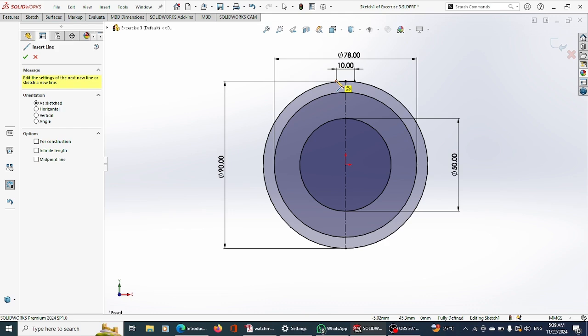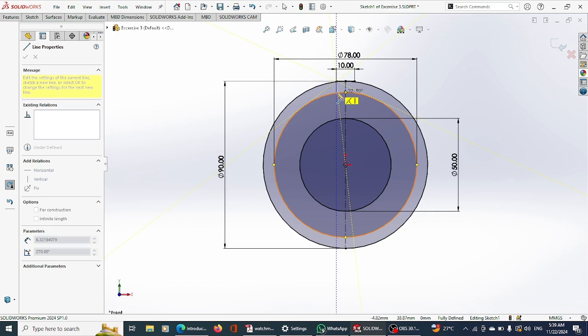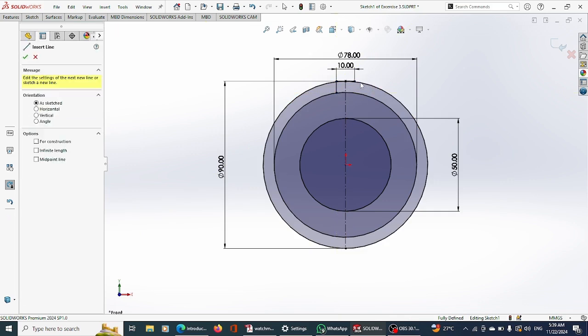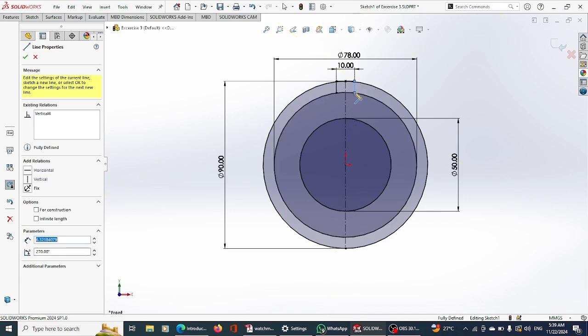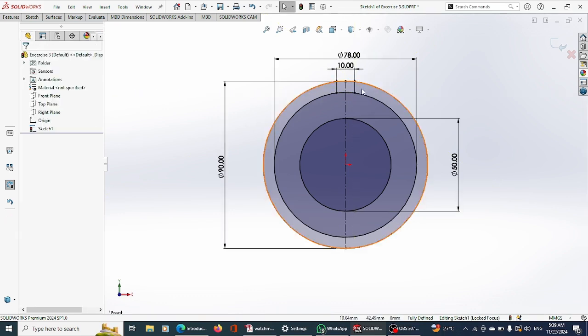Now go down. You use the key escape, hit enter to pick the tool again. Good. Down, coincident, good, and it's vertical. I'll delete this guy so that you see what happened. Escape, delete.